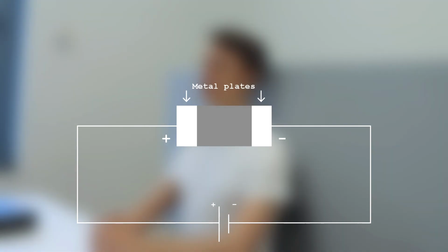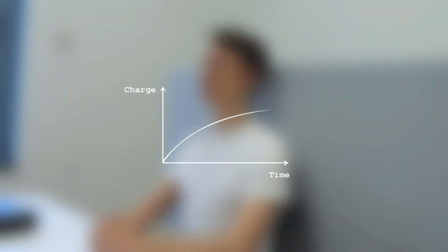A capacitor consists of two conductive metal plates which are separated from each other by an insulating layer. This layer is called a dielectric and blocks DC current from flowing through the capacitor. Instead, there is a potential difference, a voltage, present between the plates when current is fed to a capacitor due to the electric field.